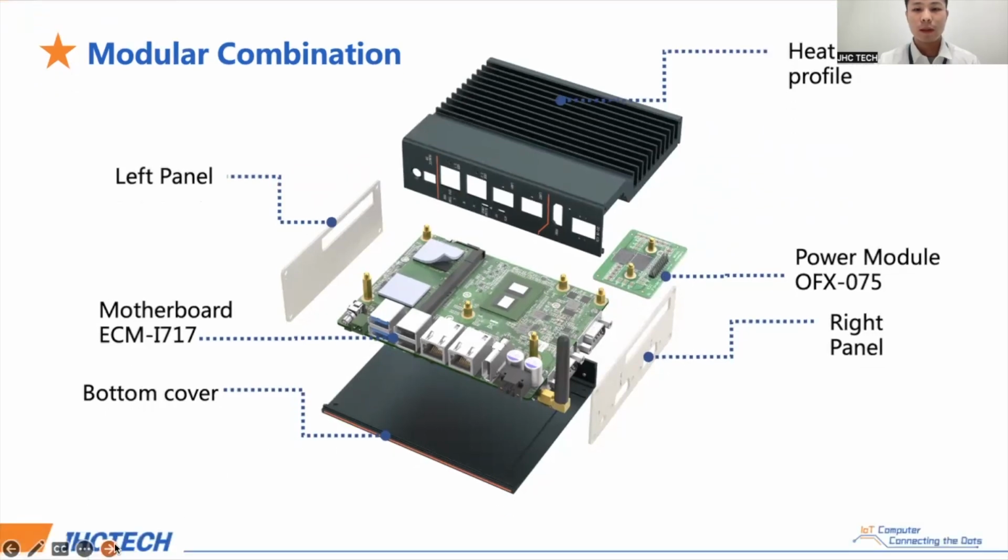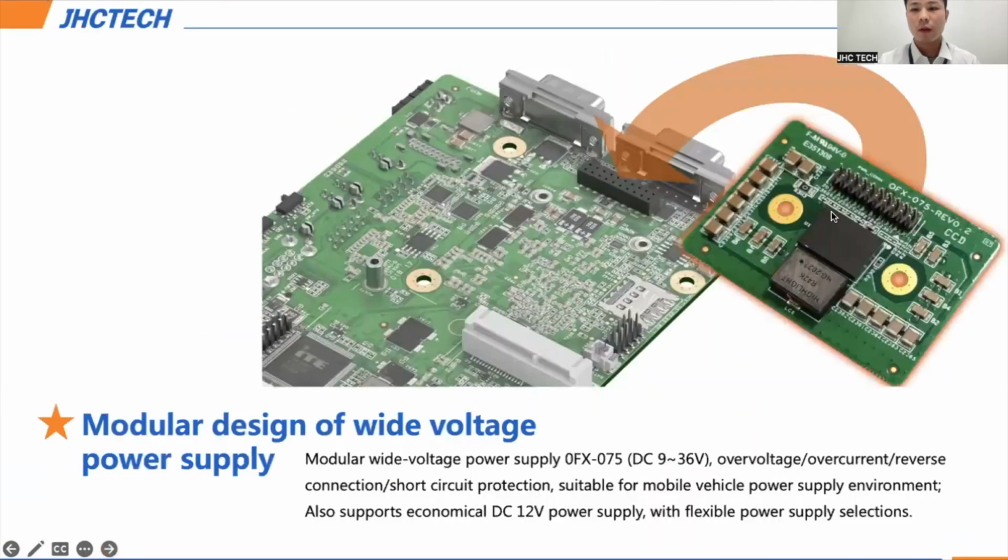I will introduce this power module. If this product is without this module, it can only support DC in 12 volts. But if we install this module on the motherboard, it can support power supply from DC 9 to 36 volts, wide power input. So there are two options of power supply.